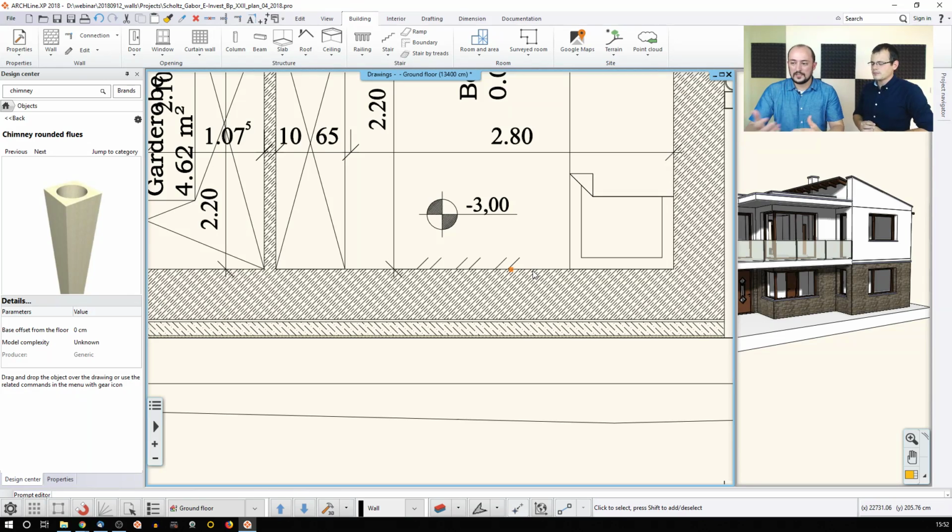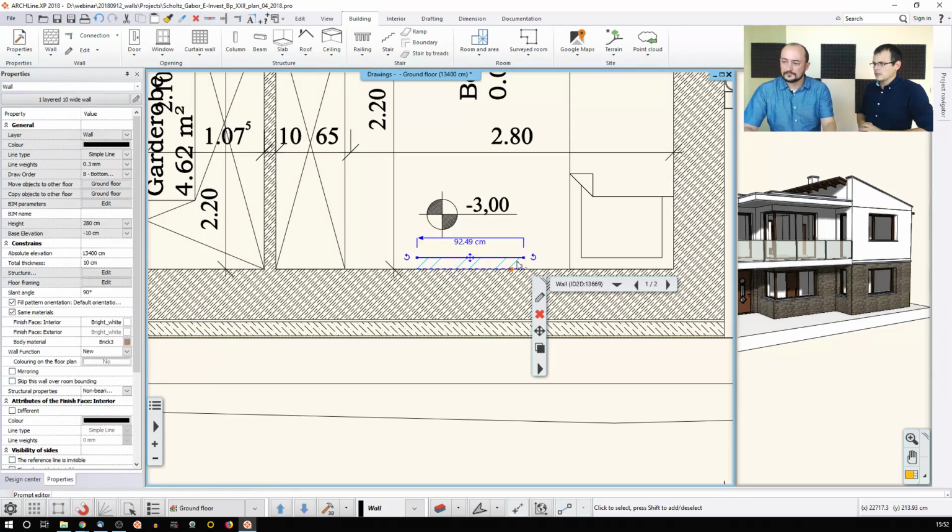And if you would like to change the visual clues of this wall, you can do that in the way that appears here. And then again, this is a wall that you can cut the contour of. You can insert certain objects in it. You can even create a bevel when the wall thickness is thinner than the rest. And for this purpose, I would like to show one specific thing, because that's actually a window property, but it changes the wall shape. Yes. Also, we have the niche tool.